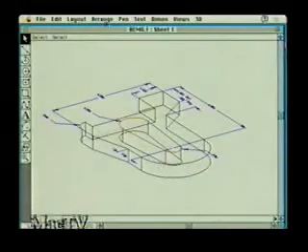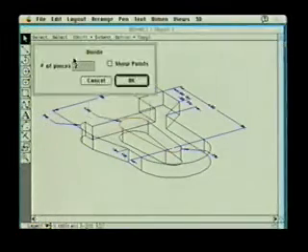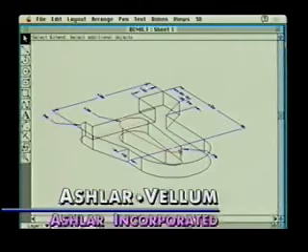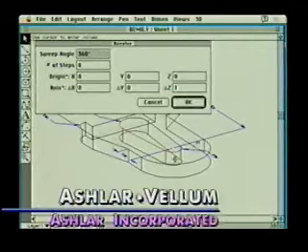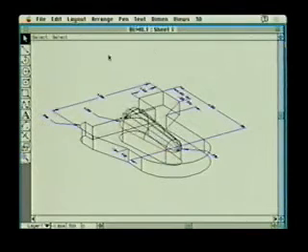Very much so. Then the other most common 2D, 3D thing that you would do is a rotate. So I'm going to divide these top objects here into 2 pieces, and then I'm going to rotate them. So I'm going to revolve this. Now when I use the revolve command, it asks for an axis of revolution, so I can just say, all right, let's go 180 degrees with 8 steps and give it an axis of revolution from this endpoint to this endpoint. And again, the drafting assistant fills in all these for me, and I say OK, and I get a dome shape on top of my part.